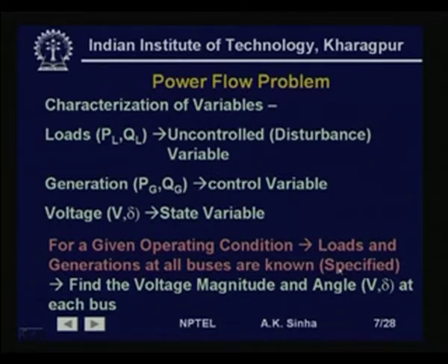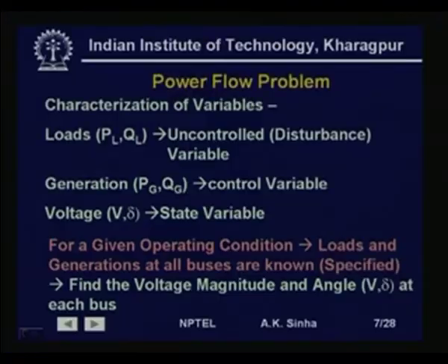That is, when we do a power flow study, we need a given operating condition, which asks what the loads in the system are at that particular instant or condition which we want to analyze. So, all the loads and the generation for that operating condition will generally be specified. Given these loads and generation, the problem of power flow is to find the voltage magnitude and angle at all the bus bars.